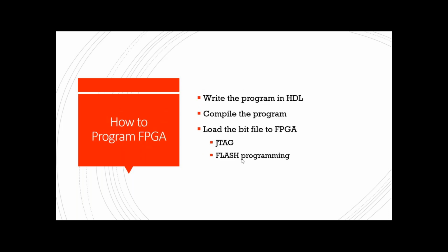So the next question is how to program that. It's the same front end between the ASIC and FPGA. It's all hardware description language. You'll be writing Verilog, VHDL or SystemVerilog code, and converting that into bit level. When I say bit level, I showed you initially the LUTs, the lookup tables. Those lookup tables we will be programming.